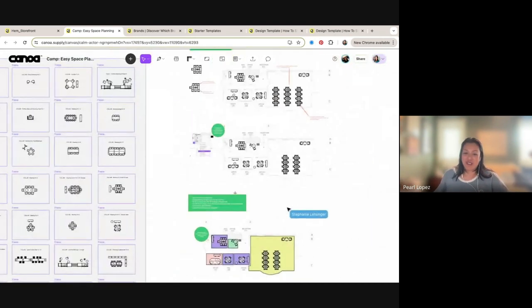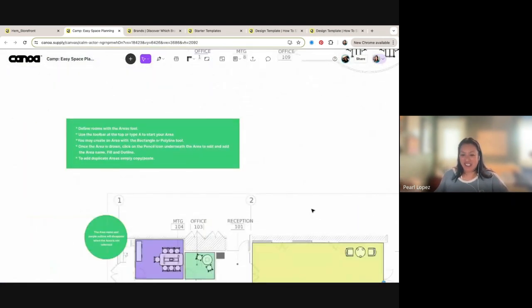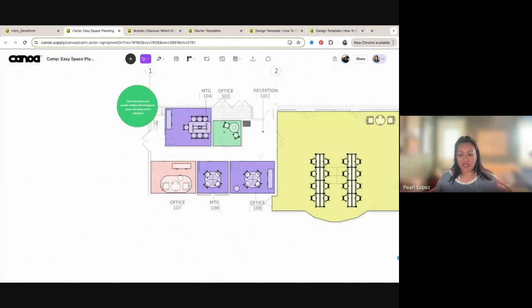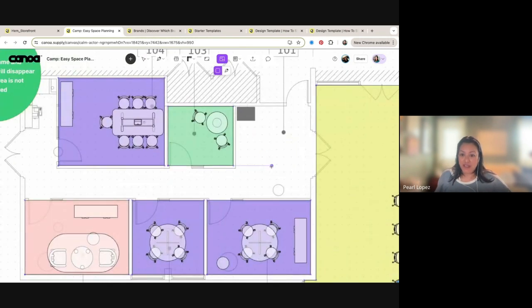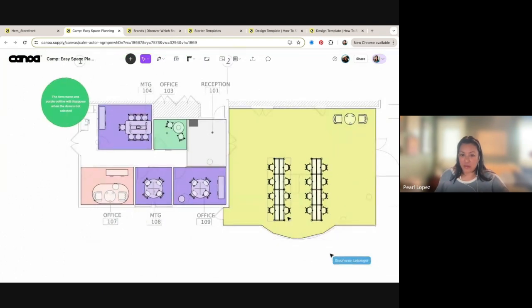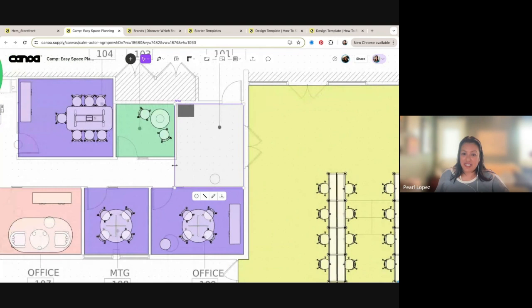There's even more you can do with this. So we've got something called areas. And what you're going to see down here is that this plan has now become color coded. And what's great about areas is not just the pretty colors, which are great because it helps define your different rooms, but when you create an area, and that's this icon here, or you can just type the A key, you're able to define the area. So you can essentially just draw, and you can do it either by selecting a rectangle, or if you've got a unique shape, you've got the pen icon, so you can create this funky curved window part. But this does define this area.